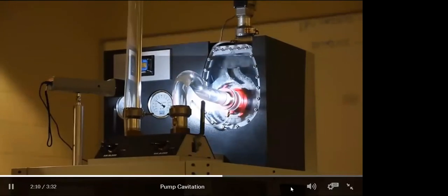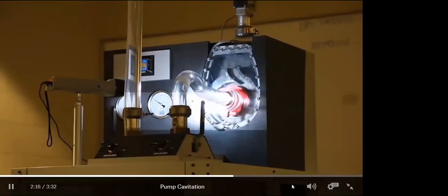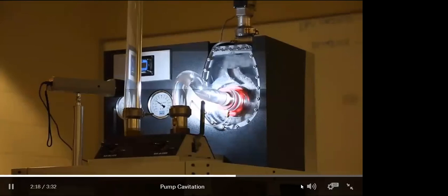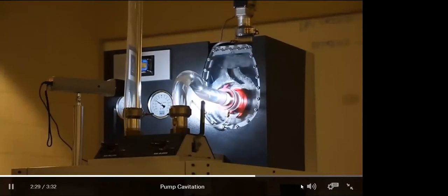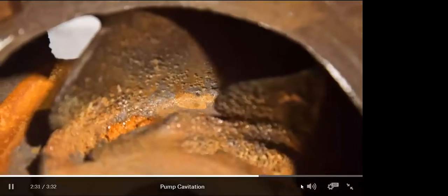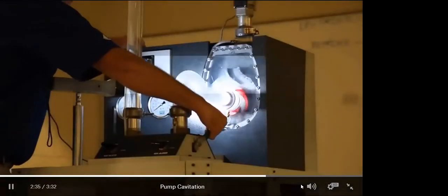And that's where the destructive force of cavitation is. When those vapor bubbles implode back into liquid, they give an energy discharge that's been measured between 80 and 110,000 psi of energy release. Okay? The tensile strength on a ductile iron impeller is nowhere near that. So what happens is you start to blow away chunks of metal at the eye of that impeller.